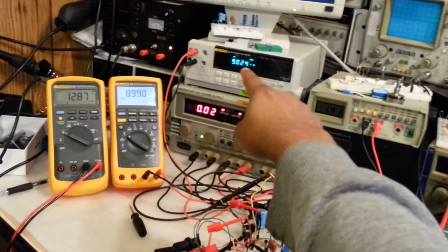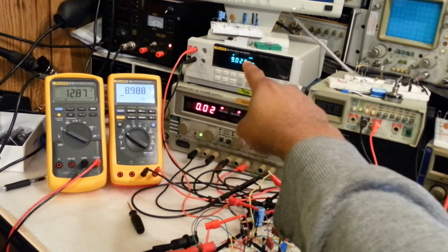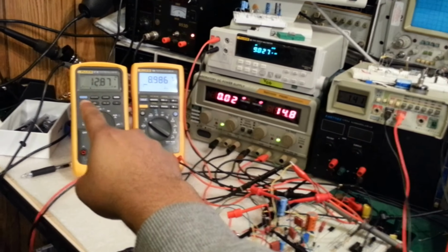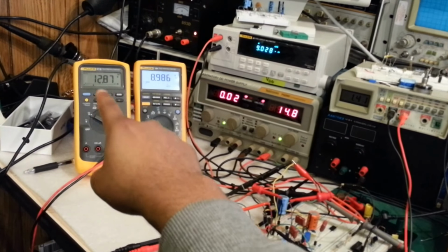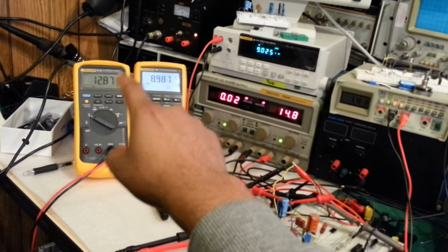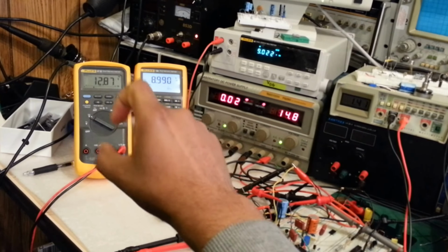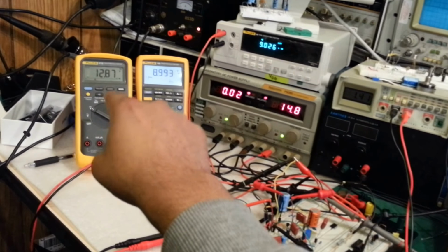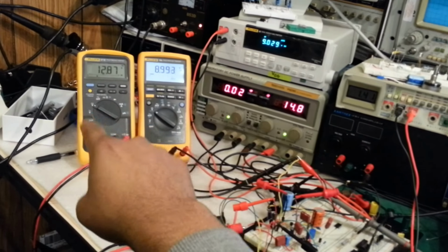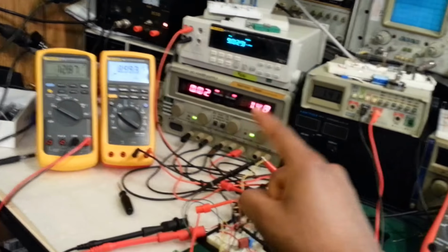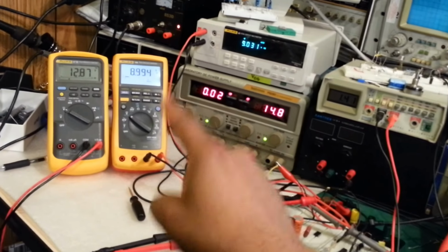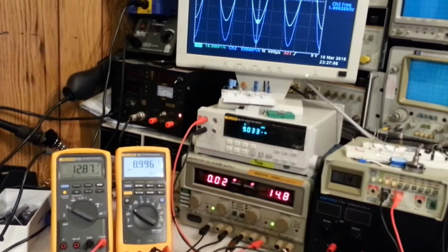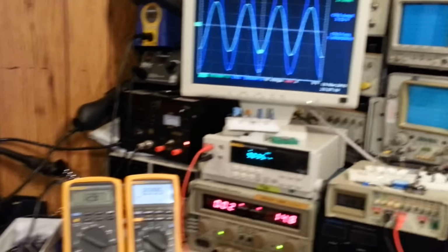will change. This one is also measuring the other side of the collector voltage of that differential amplifier, and this is the voltage across the 1.2 kilo ohm current source that we designed. This one is monitoring the voltage across it. So this one will be directly proportional. The voltage across here will be directly proportional to the current across the 1.2 kilo ohm resistor, which determines our current.